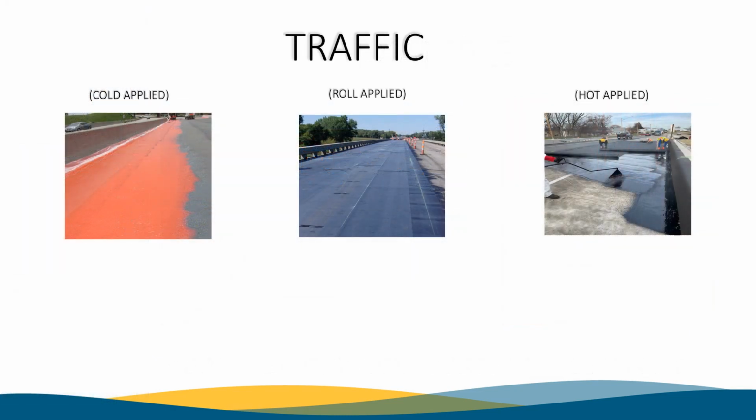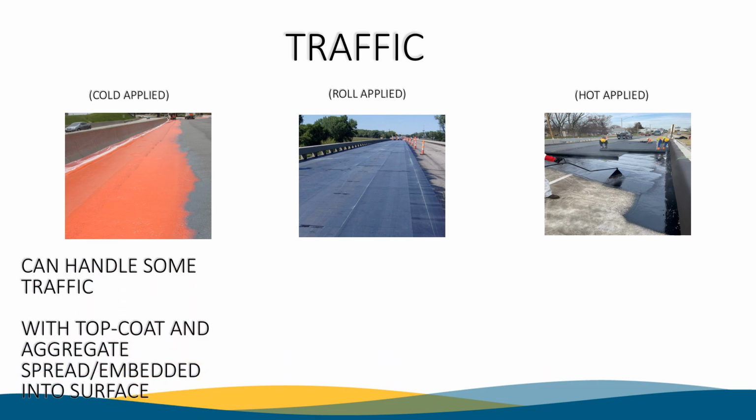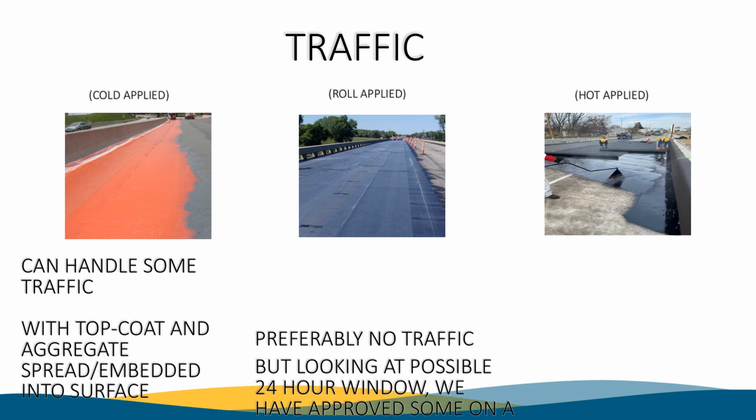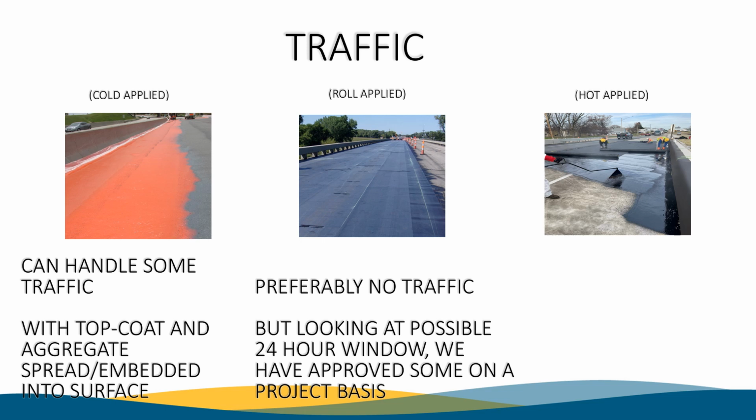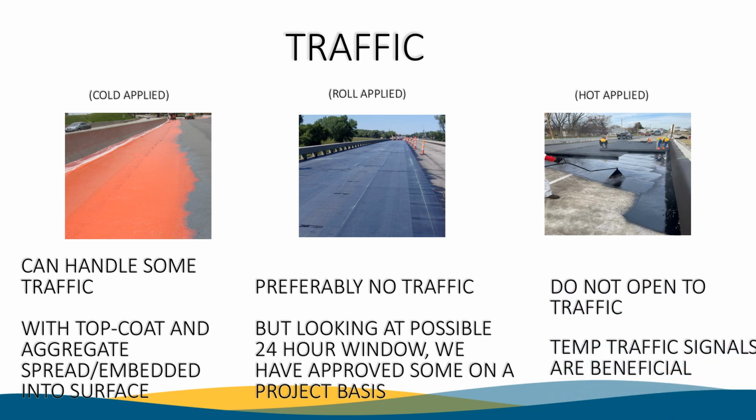After installation, they have different requirements when it comes to traffic. Cold applied can have traffic. Roll applied should not have traffic unless absolutely necessary, and hot applied cannot have any traffic whatsoever.